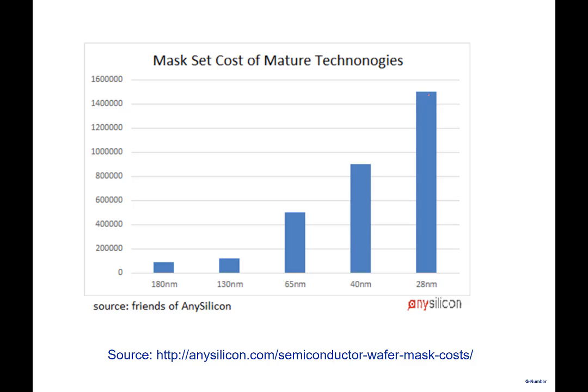The mask cost. So isn't this on an area basis? No. Producing one mask costs the same regardless of the area. So for your IC, remember, the IC may be small, but what is fabricated is a complete wafer. So you'll make multiple ICs here. So your mask covers the entire wafer, in a normal process.